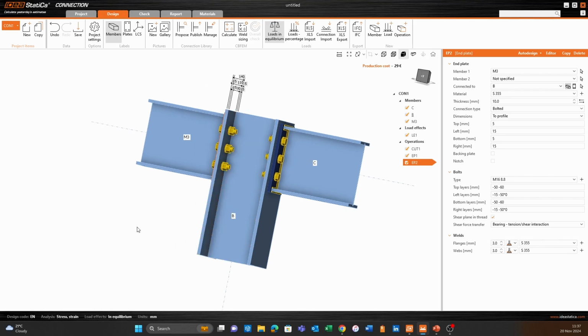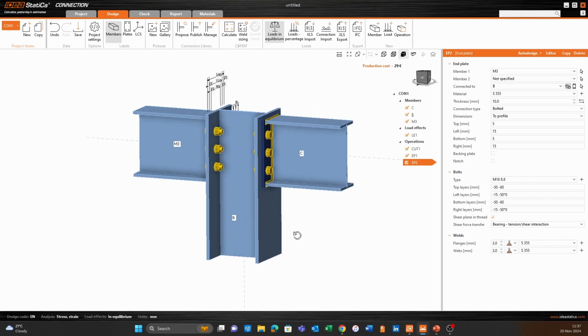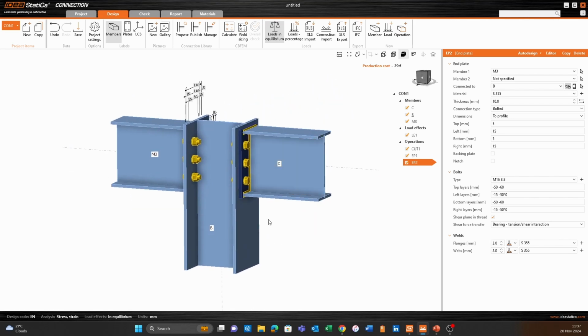That cutting operation, although maybe a bit misleading initially, is very helpful, and it's exactly that operation that you'd use to extend your column. Don't go through the effort of extending the column in your analysis model. It adds some additional things that are quite weird, meaning that it potentially picks up there's another connection at the top there, whatever it might be. This is the right way to do this.